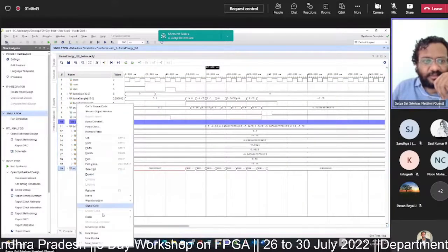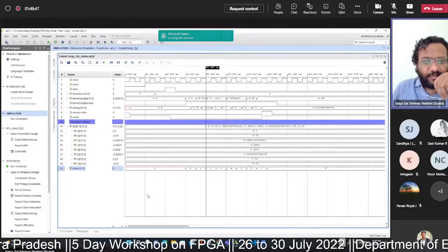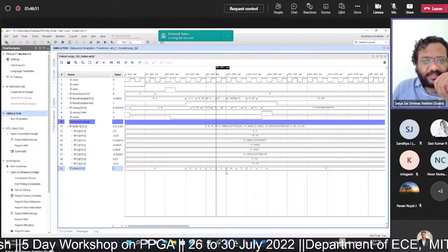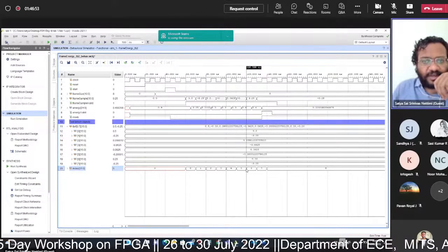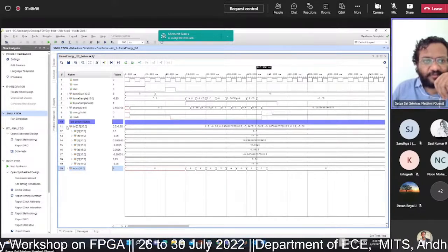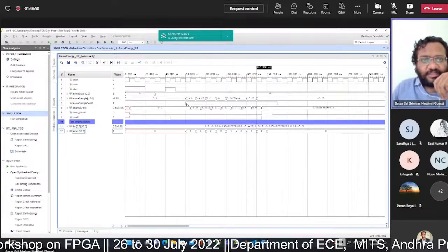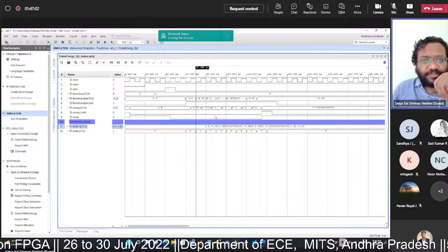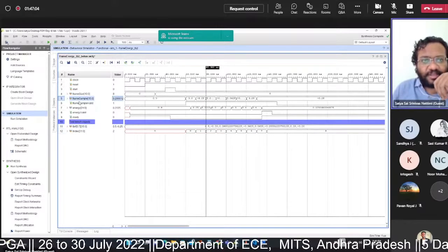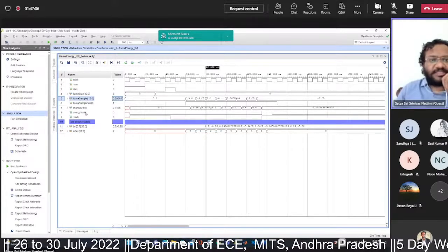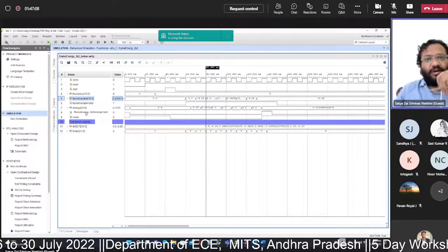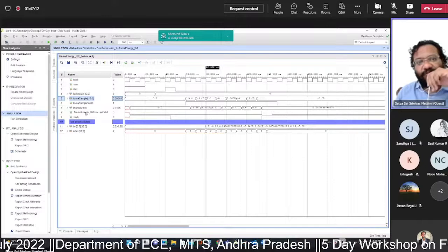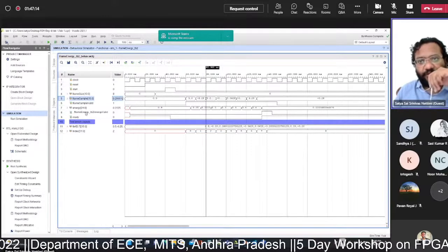This index is used to run the for loop and also serves as an addressing index to fetch the data from the test bench register file. Each and every sample is being read from the test bench register file, and that sample is fed on to the frame sample input of the test bench, and through the test bench input it is reaching the frame sample input of our module.